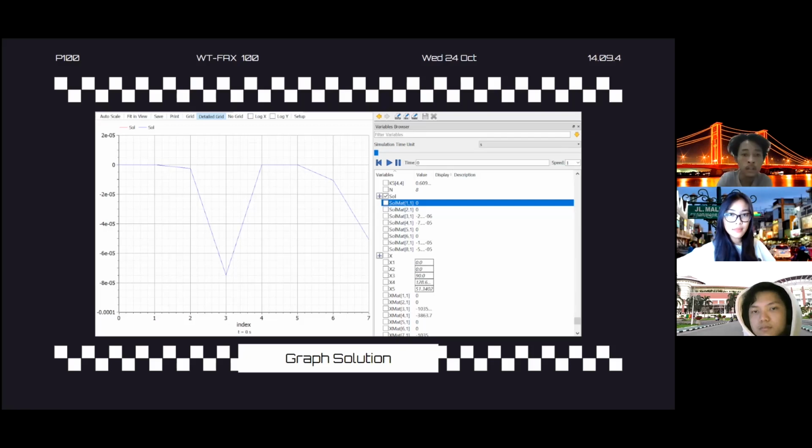As we can see from the previous section, I will conclude the step-by-step process for finding the displacement in the 2D trusses case. From the start, we must input the parameters and the geometry: A, E, F, L, and the angle. Then we must find the stiffness matrix and the error.